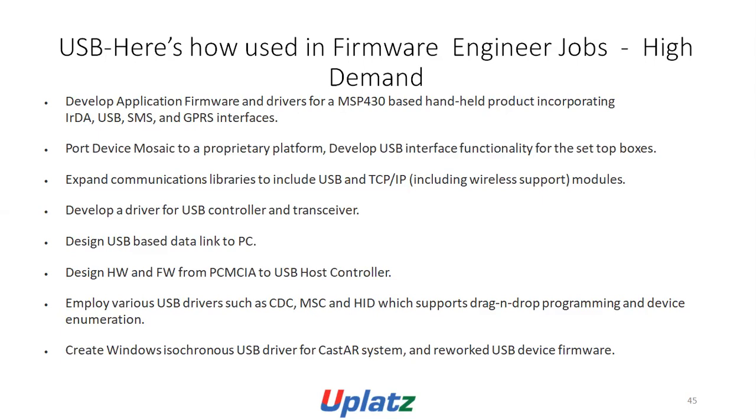Develop a driver for USB controller and transceiver. Design USB-based data link to PC. Design hardware and firmware from PCMCIA to USB port controller. Employ various USB drivers such as CDC, MSC, and HID, which supports drag and drop programming and device enumeration.